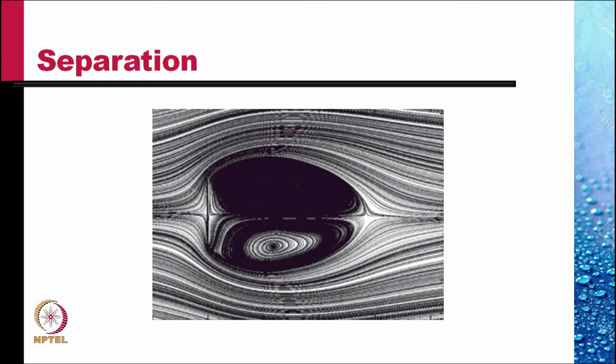Similarly, we have this plate held perpendicular to the flow. The flow separates at this tip, because if the flow was to proceed down the back side of the plate, the pressure would have been increasing, and the flow separates, forming two large attached vortices. Because the Reynolds number is not very high; if the Reynolds number was very high, these vortices would have been washed down, and we would have a region of turbulence in that place.